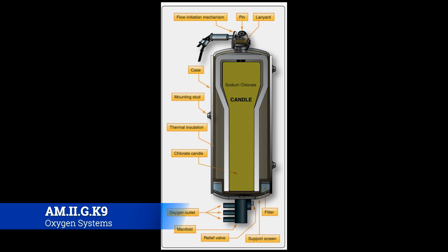You pop the candle, and it's going to get really, really hot, so you definitely don't want to hold it in your hand or put it in a place that's sensitive to heat. Put it somewhere it can get hot and not char anything else. It's going to produce oxygen for about 10 to 20 minutes, depending on the situation and the individual candle in question. So you've got about 10 or 20 minutes to get to below, say, 12,000 feet, to where you can actually breathe the air again.